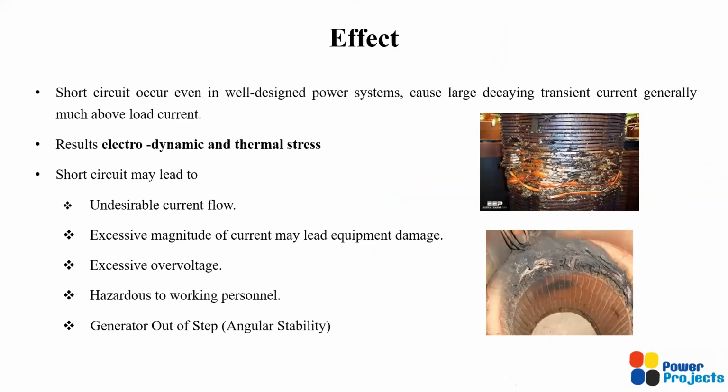Okay, what are the effects or impacts of short circuit? As I told, even in a well-designed power system, there is a probability for a short circuit. This short circuit results in a large current, and of course, this current decays over the period. It results in a huge thermal stress, because if there is a fault, the current might be 50 times or 100 times the full load current. So definitely it creates a thermal stress. And of course, it creates electrodynamic stress as well on all electrical power system equipment.